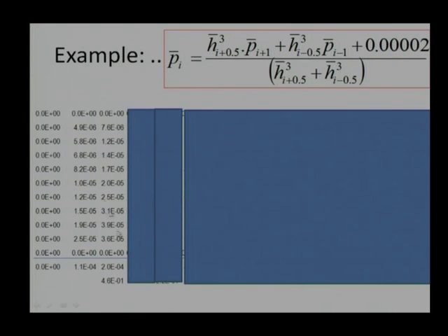The interesting thing we can observe here is that earlier the pressure was maximum at the node one lesser than the boundary node. However, in this case you can see the maximum value of pressure is happening at node number 9 itself. Earlier the pressure was maximum at node number 10, here the pressure maximum is at node number 9, and this is what the boundary condition is affecting. The boundary condition is 0 here, 0 here, it is affecting the results, and that is required also, because we know the pressure profile in this kind of surface will be parabolic. Otherwise, it will not turn out to be parabolic, it will turn out to be some linear profile at the exit.